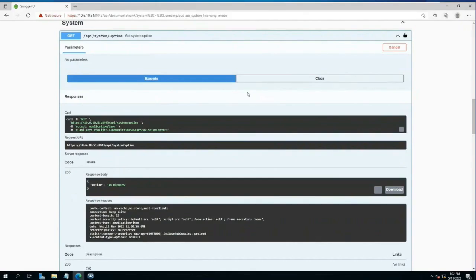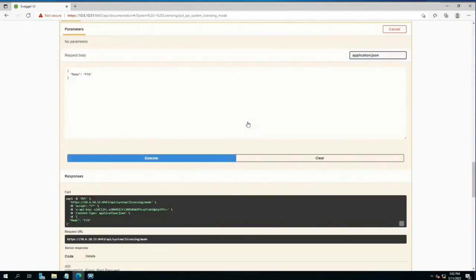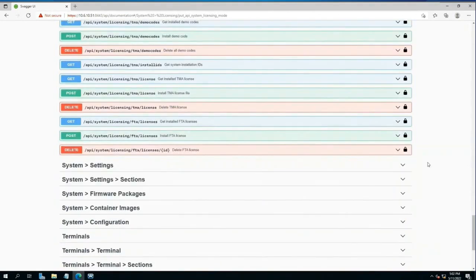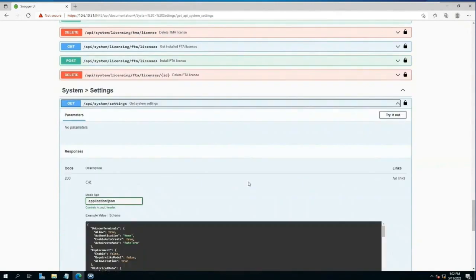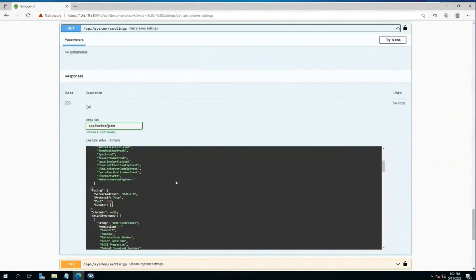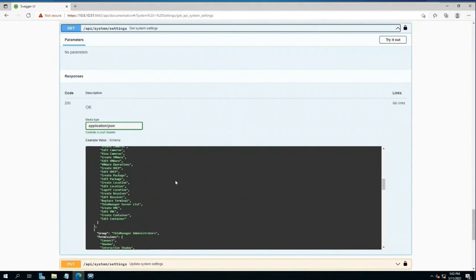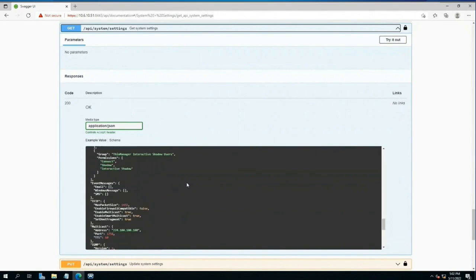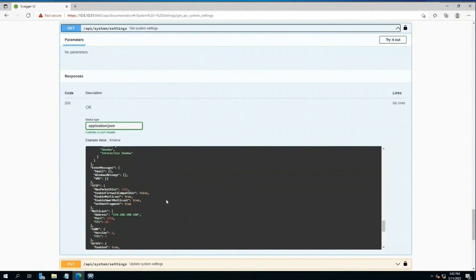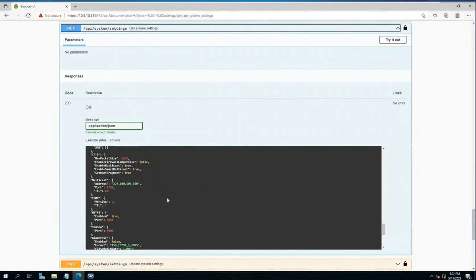So we could see the ease of the documentation and what that's providing for us. There's obviously more complicated examples or more in-depth examples. We could look at getting all of the system settings or the different system attributes. What are our syslog settings? Do I want to allow the creation of users? What are the permissions associated with my ThinManager server? Who has which permissions? Again, I could change the ports, completely be able to configure my system all without ever having to launch the ThinManager user interface.